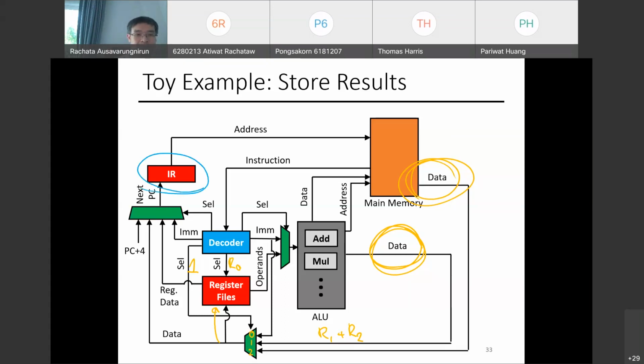Next PC, right? So what should the decoder select for the next PC? Let's assume this is 0, 1, 2, and 3. We are not jumping, right? We are not jumping to a register value. We are not jumping to a line in your code. We are not jumping to any result from your ALU. So which one are we selecting?